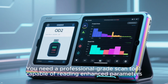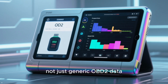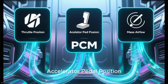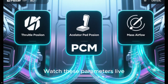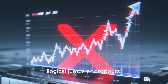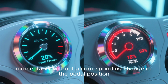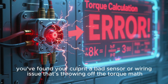You need a professional grade scan tool capable of reading enhanced parameters, not just generic OBD-II data. We need to focus specifically on the primary inputs to the torque calculation: throttle position, accelerator pedal position, and mass airflow. Watch these parameters live. Are they smooth? Do they show sudden, illogical jumps or dropouts? Pay close attention during acceleration and deceleration. If the throttle position jumps from 15% to 50% momentarily without a corresponding change in the pedal position, you found your culprit: a bad sensor or wiring issue that's throwing off the torque math.